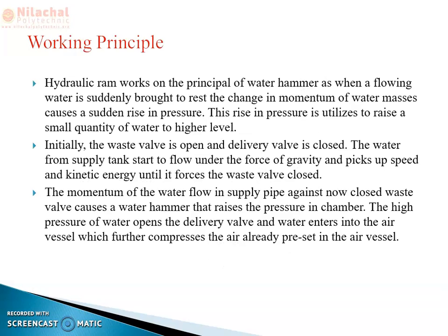Let's come to the working principle. The hydraulic ram works on the principle of water hammer, as when the flowing water is suddenly brought to rest, the change in momentum of water masses causes a sudden rise in pressure. This rise in pressure is utilized to raise a small quantity of water to a higher level.